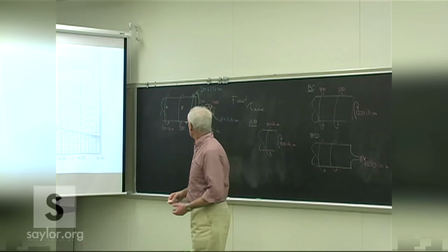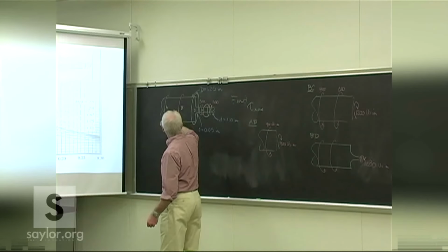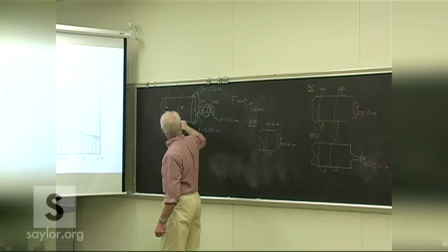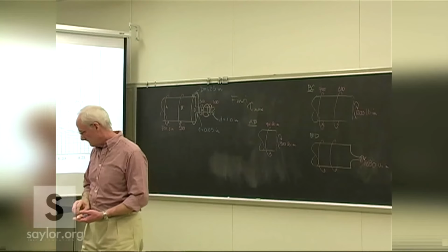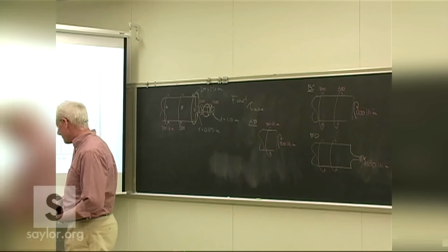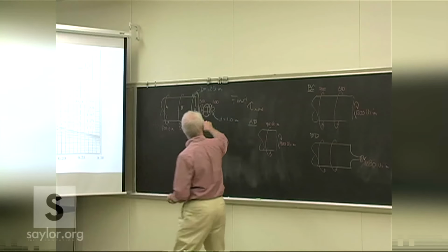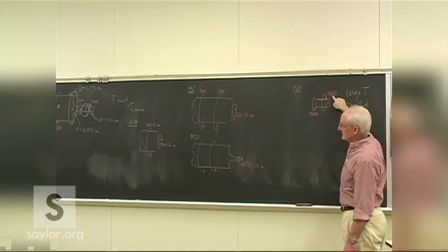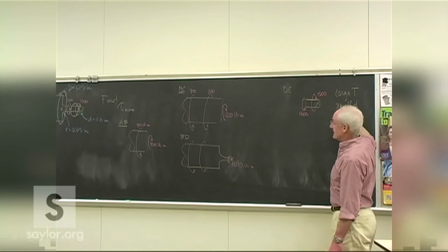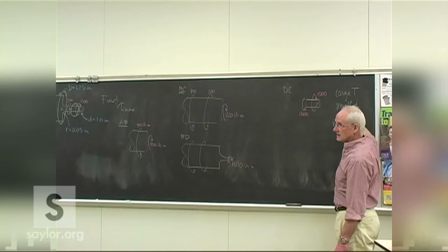We know the other areas are not as much a concern. The loads are less and the diameters are greater. You wouldn't have to do... Well, you should, because the largest load is near the end of that shaft, in the smallest diameter.